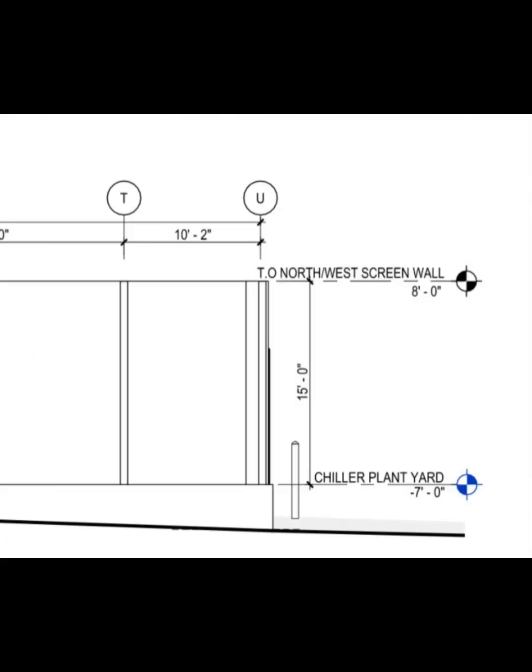Elevation control comes from the south wall at U-line. This is top of slab and top of U-line retaining wall. Calculate all of your footings from the top of north screen wall elevation. Confirm your information jives with HIT and the excavation contractor's bedding.